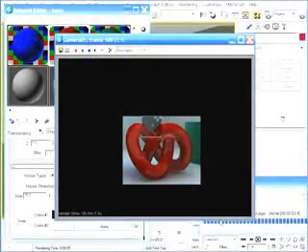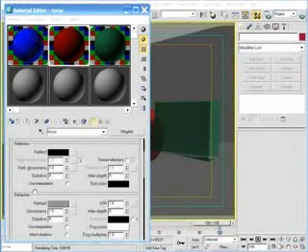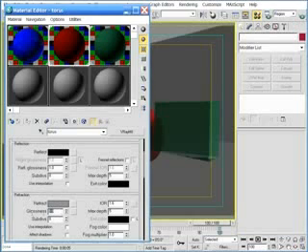The last area of materials that I want to point out at this point is a feature that causes a great deal of confusion among VRay users, and that's reflection and refraction interpolation. What they do is simply speed up the process of calculating each of these blurry effects. And these two features are fairly advanced, but they're worthy of mentioning at this point because of the tremendous impact they can have on rendering times when they're used properly. One of these is actually fairly easy to use, and the other can be quite frustrating. Let's look at the easy one first, refraction interpolation.